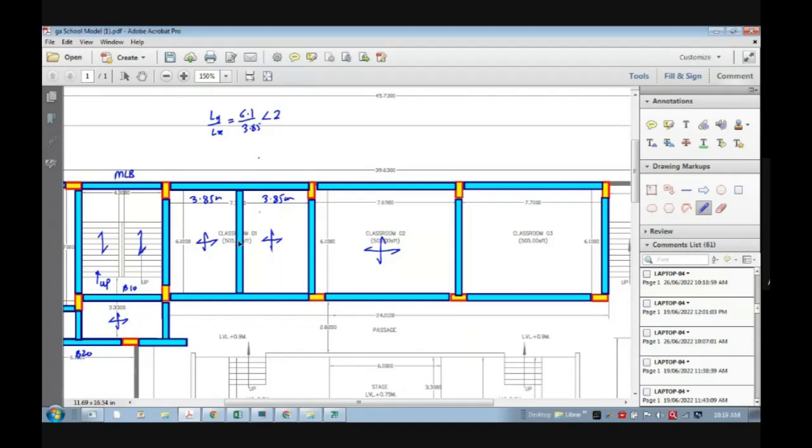And even though there is a beam in the ceiling, you see what's wrong? Nothing wrong, isn't it? Because that aesthetic part in the classroom is really not a big issue. Should not be. So we can convince the architect: I want this beam because the slab thickness will be more and there will be a vibration issue. So we can answer the questions given by the architects. So let's say this is one of our choices, and for study purposes I will keep this also. But as a structural engineer, I will be happy with such solutions.